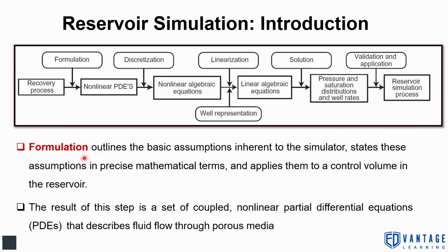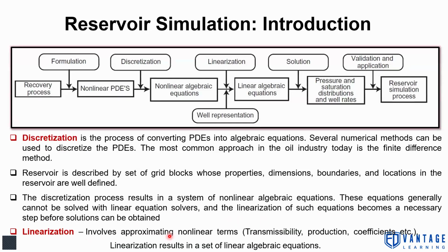So formulation outlines the basic assumptions that are inherent to the simulator, states these assumptions in precise mathematical terms, and applies them to a control volume in the reservoir. So control volume is the volume I have chosen to do simulation to understand how the flow is happening, what kind of flow is happening, and how this flow is affecting the pressure distribution and saturation of oil distribution. The result of this step is a set of coupled non-linear partial differential equations that describes the fluid flow through porous media.